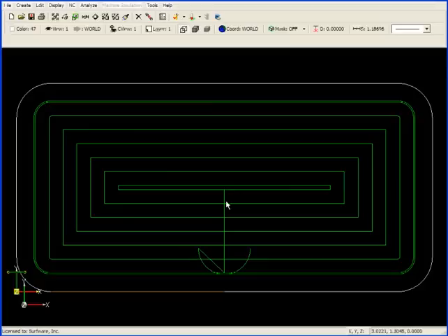part and move out in a straight line to the next cutter path, and again and again. We have a lead in and lead out move against the wall on the final pass, and each time we change direction, at least for the middle passes, we're coming to a sharp point and then continuing in another direction. Now, if I want to change this, it's very easy to do in SURFCAM.